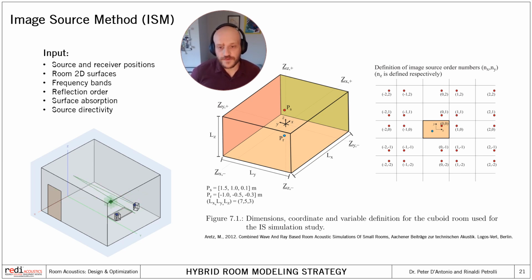The method is conceptually similar to the traditional technique where you stand by a wall with a mirror to locate the point where you can see the speaker, which will represent the specular reflection point at that wall. The image source method extends this by calculating multiple reflections across all surfaces for multiple orders of reflection. A first-order reflection involves just one reflection point, while a second-order reflection involves two, and so on.